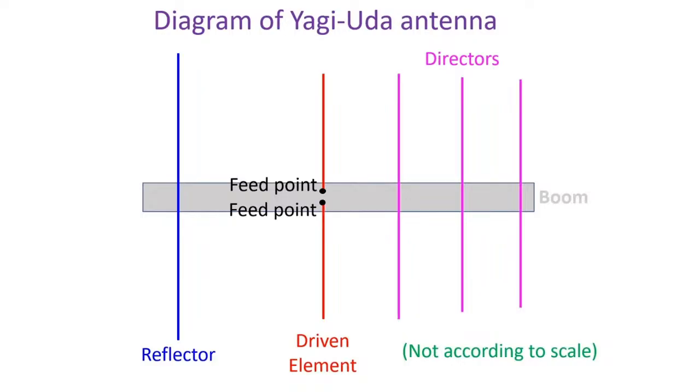Spacing between the elements may vary from quarter wavelength to 1/10 of a wavelength depending on the design. Radiation pattern of Yagi-Uda antenna is along the axis perpendicular to the plane of the elements towards the direction of the directors. As the parasitic elements have zero RF voltage at the center, they can be directly attached to the boom, but this will electrically shorten them and usually a correction in length is needed to cover this. There are versions in which all elements are insulated from the boom as well. The two halves of the center-fed dipole have to be insulated in the location of the boom.